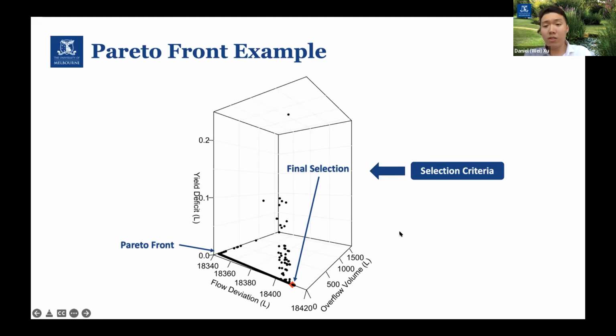The selection criteria is basically that we prefer the environmental flows on top, then the flooding, and then we have the last preference on the supply. And here the red dot shows, out of those 500 sets of results, the final selection in these 500 sets of predictions. After you have an understanding of this one particular selection, we implement it in the next time horizon before the whole objective function is recalculated, just like the same structure as model predictive control.